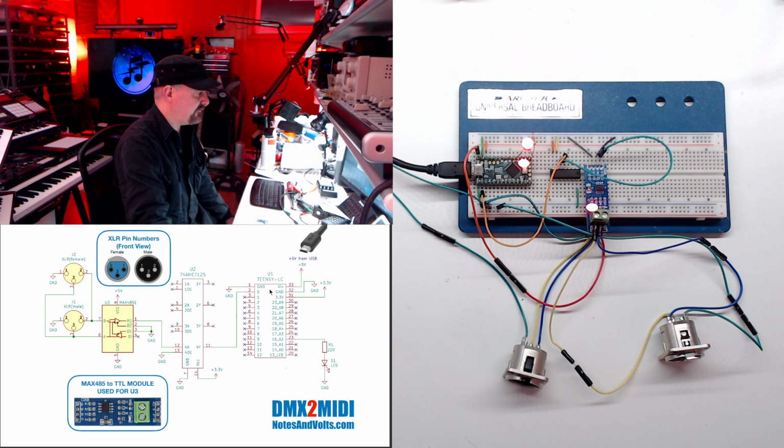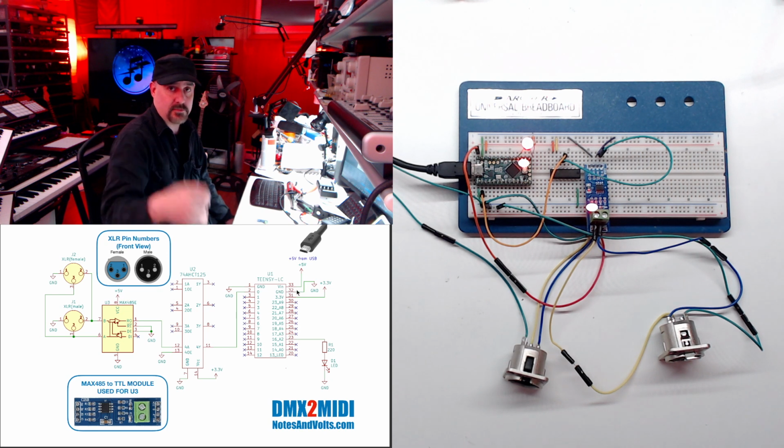So even though we've got 5 volts coming into the Teensy from our USB, the Teensy has a built-in regulator that's going to cut that voltage down to 3.3 volts, and that's what's going to run the processor on the board. That 3.3 volt regulated power will be available at this pin right here, and we can take that voltage out and power any 3.3 volt devices on our board. We also have ground pins here and here. They're both connected together, so you can use either one or both.